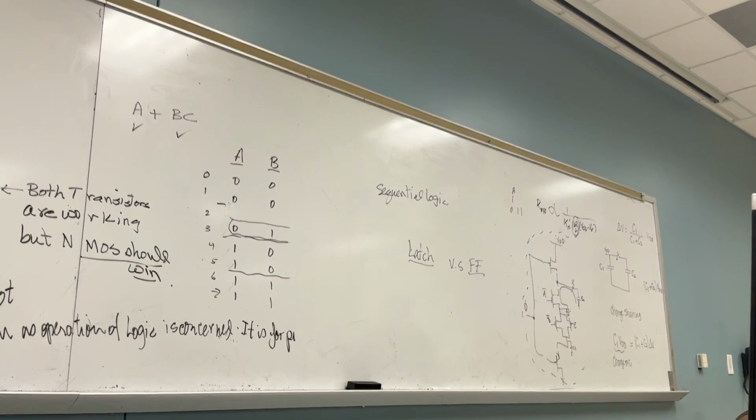First of all, what does latch mean? Hold. You are trying to hold on to some value of the input. Store it. Clear? The latch is level triggered, which means what? All it needs is what? High level of the clock or low level. It's level triggered. Whereas the flip-flop is edge triggered. Did you get it or not?